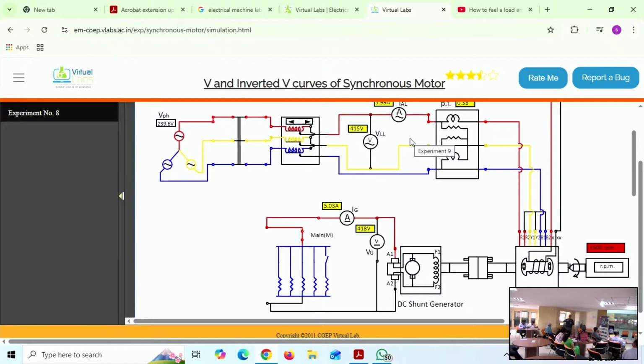As you start loading, he was putting his hand. You see the angle: you are applying some brake, so the rotor axis is falling behind the stator axis, but they are magnetically coupled and rotating at a constant speed. That's how they are synchronously bound and revolving at synchronous speed.